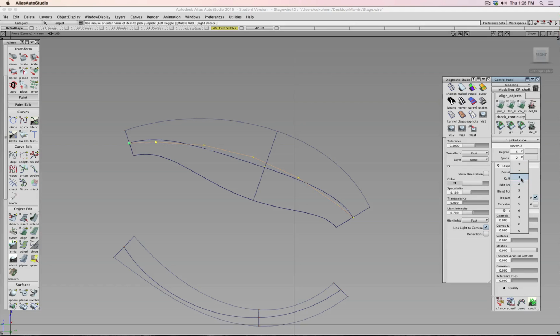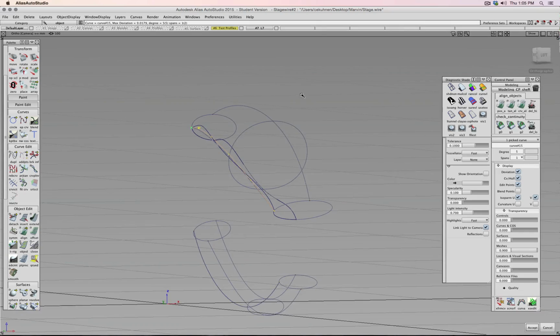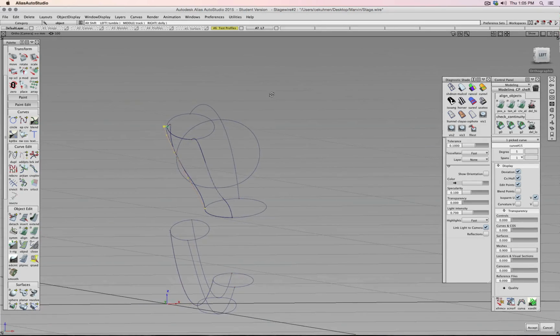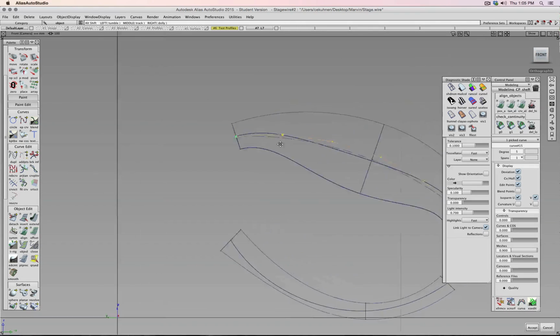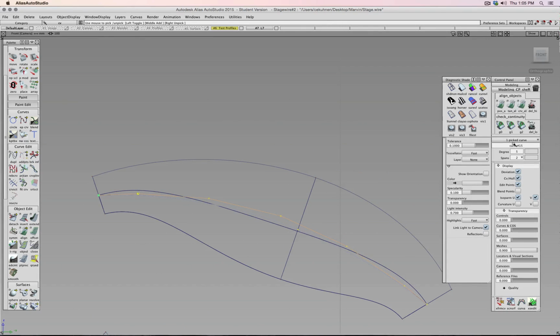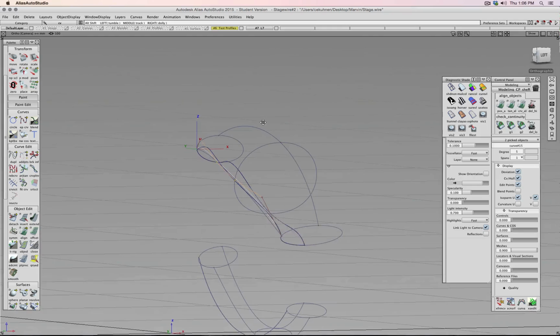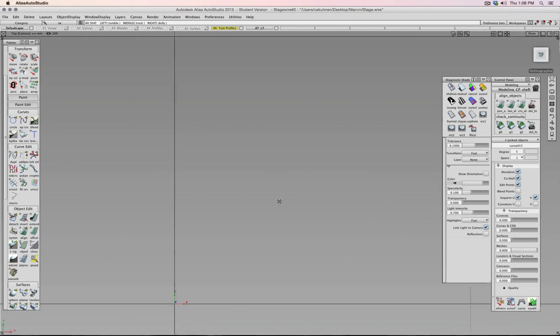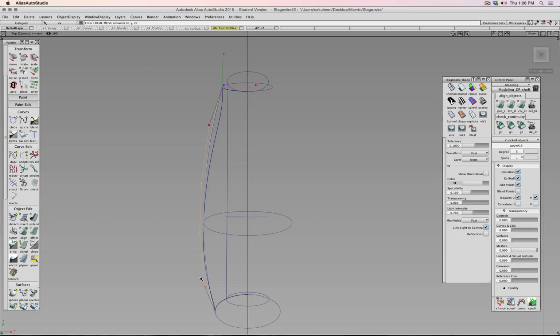So this one, let's change this to a degree 1, let's go back, degree 1, and then let's push and pull those CVs. Maybe here I move this one up a little bit, and you see I try to hit that original curvature a little bit. And yeah, do I go down? Maybe I have to go down a little bit. And let's take a look from the top view. That's going to be the most important one, how those curves make the transition that way.